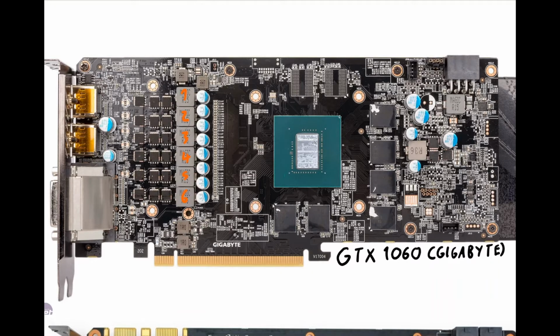So physically there are 16 phases, but functionally it is 8 phases, and I always talk about how it is functionally for the card, if I say it has that many phases. But back to this card, we can't see any doublers, and it wouldn't really make sense to run a 3 phase on a GTX 1060, so I'm going to say this is a 6 phase. If you have this card in your hand, definitely look up the PWM controller and find out if I'm right.